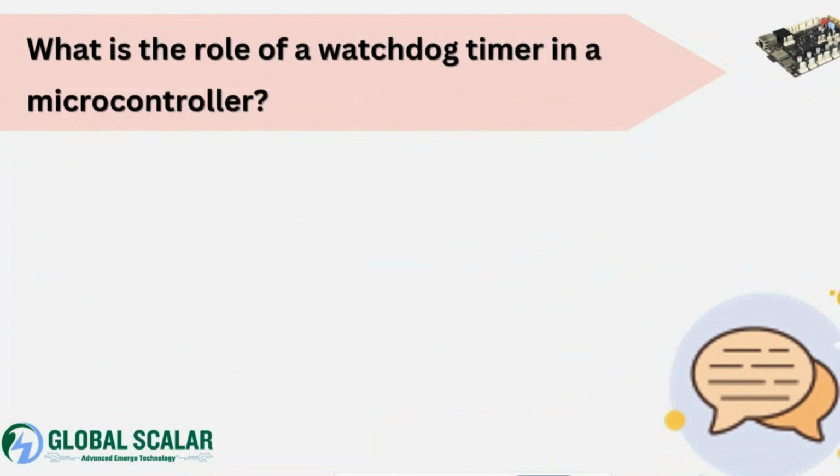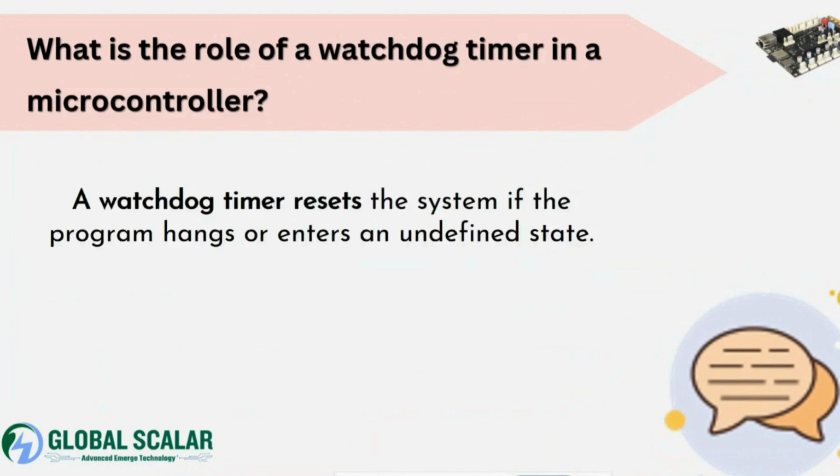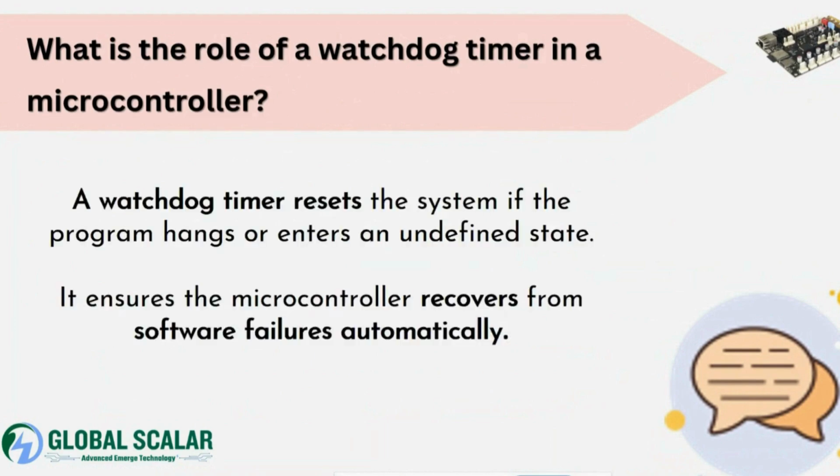What is the role of a watchdog timer in a microcontroller? The watchdog timer will reset the system if the program is halted or the hardware is not responding properly. We need to ensure that the microcontroller recovers from software failures automatically if it is halted or blocked.